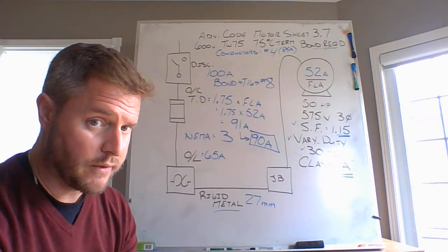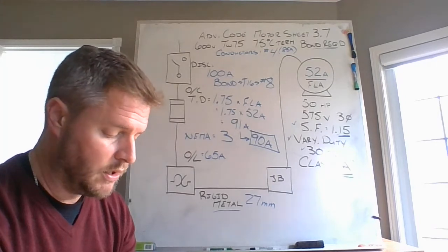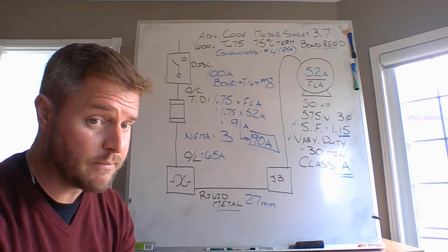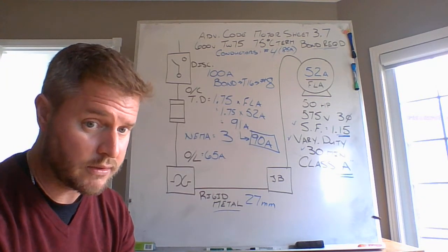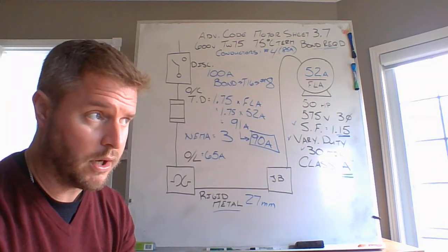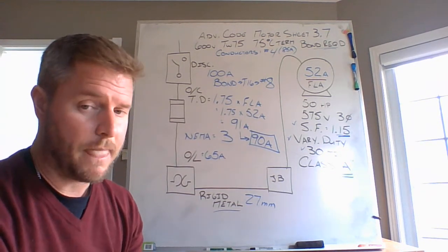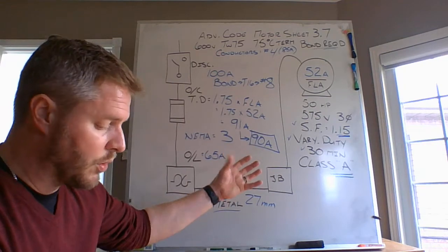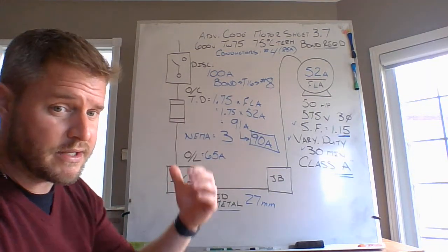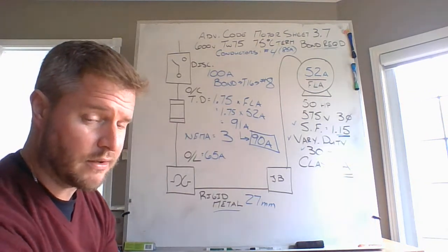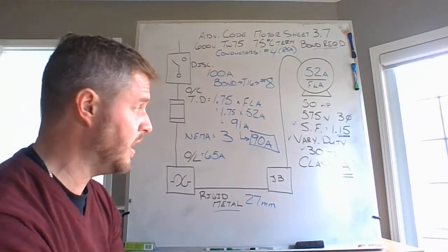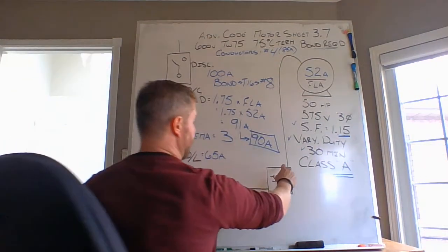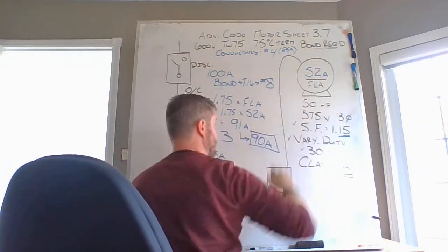So it's all the interpretation of the rule and how you have to understand this one. First of all, they're looking at temperature ratings in excess of 75 degrees Celsius. Well, for this specific motor, we are using 75 degrees Celsius rated conductors. And we are using a Class A motor, whether it's totally enclosed non-ventilated, or open drip proof, doesn't matter. So for this specific motor, this rule doesn't necessarily apply because this motor isn't going to exceed 75 degrees Celsius. We're not running 90 degrees Celsius conductors. We don't necessarily need to follow this exact rule when we are looking at this connection from junction box to motor.